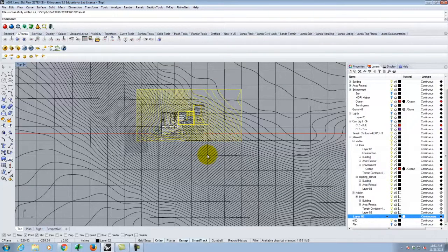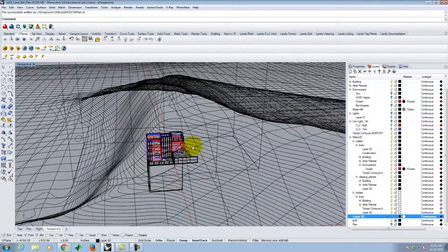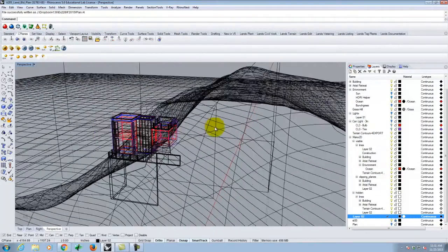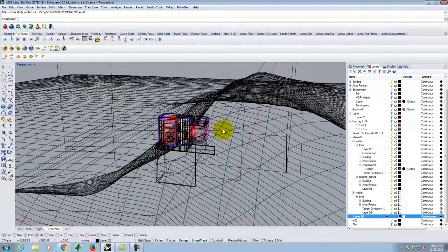Exactly the same thing we did with the elevation view, except we did the section before we created it. So now if I jump back into my perspective view here, and we start to look at this, if I'm going to do a rendering, remember V-Ray doesn't recognize the section tools, which is very unfortunate. So I'm going to have to go back through the steps that we did with the section, where I used that big plane and I split my objects, and then I converted some of them to that see-through material to do the rendering. So I'm going to go ahead and do that.